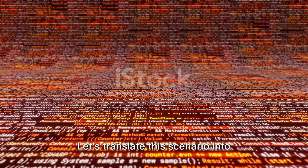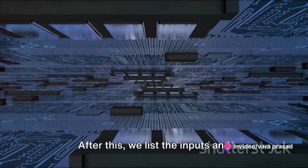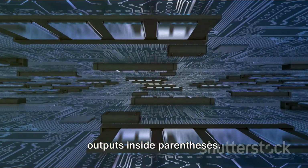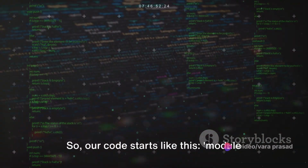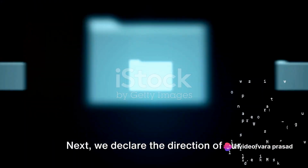Let's translate this scenario into Verilog code. Start with the keyword module, followed by the name of the module. Let's call our module flip-flop. After this, we list the inputs and outputs inside parentheses. For our scenario, we have one input, the switch, and one output, the light. So our code starts like this: module flip-flop, switch, light.